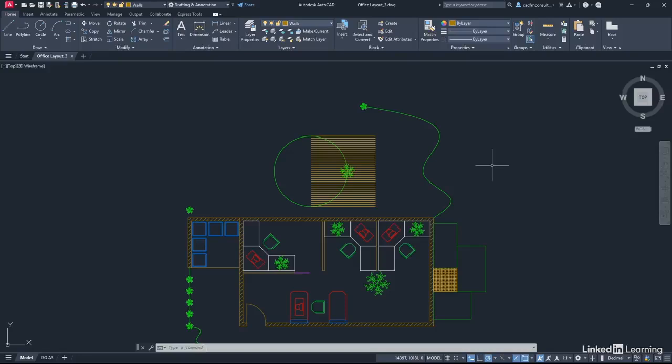Now, you'll notice up at the top, above the actual office building itself, we've got some lines, a circle, and a spline. We've also got a little bit of vegetation kicking in as well. Don't worry about the vegetation. We'll look at that in the next video. What I need you to look at is the spline and these lines here and this circle here. We're going to take a look at the trim and extend commands when we're modifying geometry in our AutoCAD drawings.